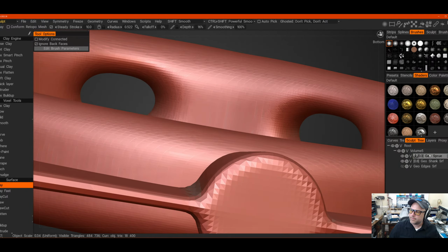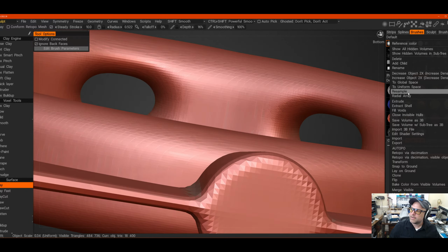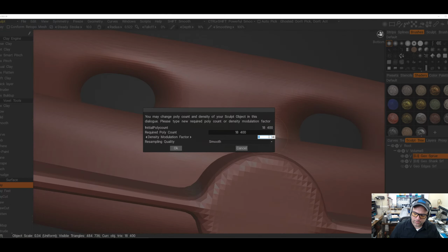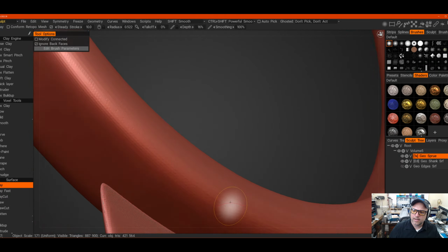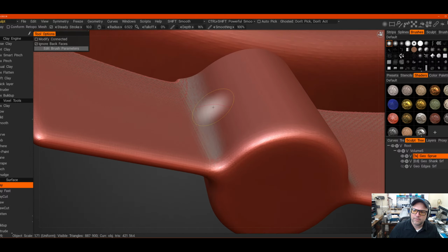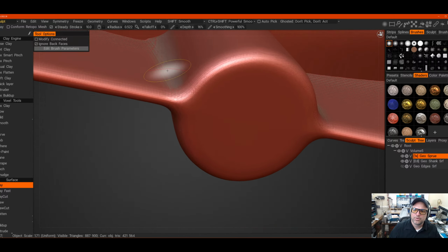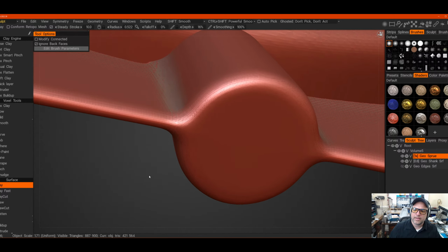That is a nice little fillet. And then we go back, resample. So I did 0.2, which is 1/5, go times 5 to get it back to the resolution of the scene. And now we've got plenty of detail and a nice smooth looking fillet.